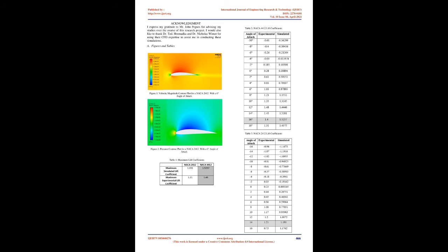For results and discussion. The data provide useful insight regarding the maximum lift coefficient, or the lift coefficient obtained during a stall. These results provide not only data about the given airfoils, but they also provide information on the combination of parameters that optimizes the lift coefficient. For instance, the NACA 4412 has the greatest lift coefficient, which corresponds to the greatest lift force. The only geometric parameter that differs between the NACA 2412 and the NACA 4412 is the maximum camber position, which is denoted by the first digit in the NACA 4412.